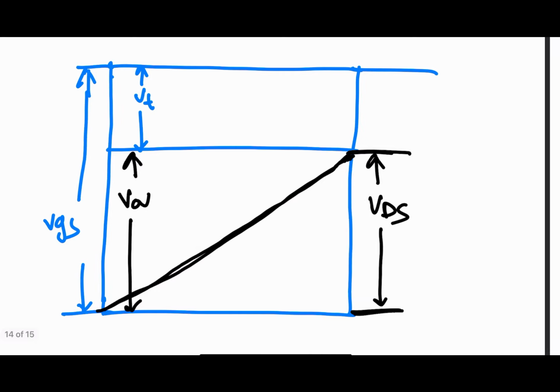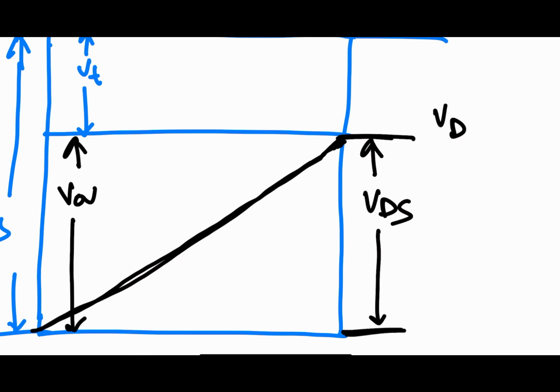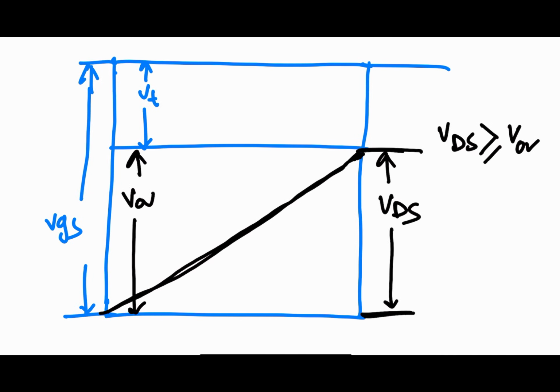When the pinch-off condition comes, when VDS is greater than or equal to VOV, then the MOSFET will be in the saturation region.